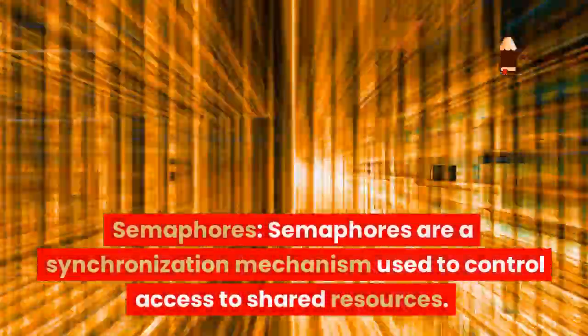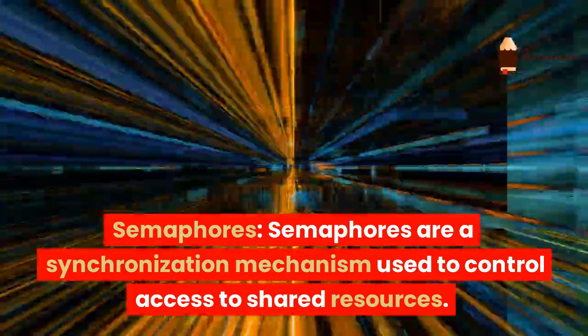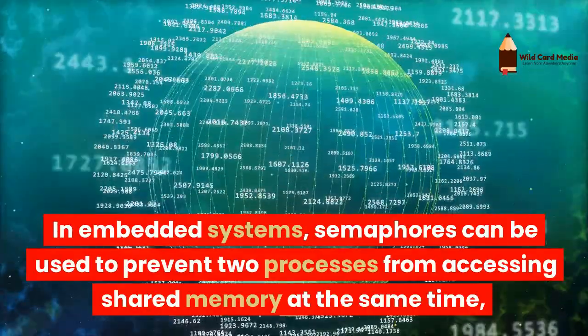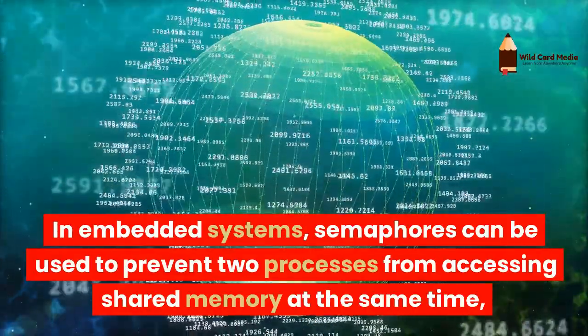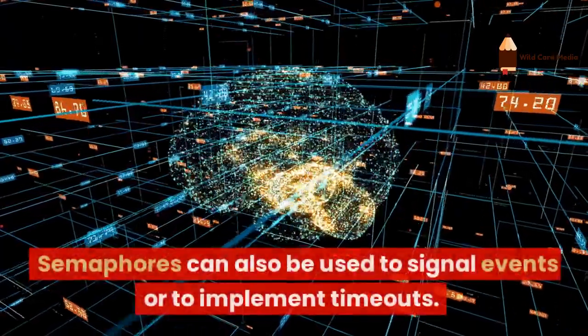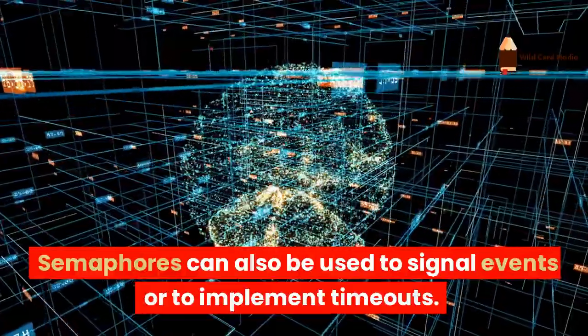Semaphores. Semaphores are a synchronization mechanism used to control access to shared resources. In embedded systems, semaphores can be used to prevent two processes from accessing shared memory at the same time. For example, semaphores can also be used to signal events or to implement timeouts.